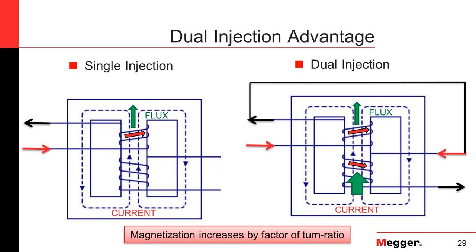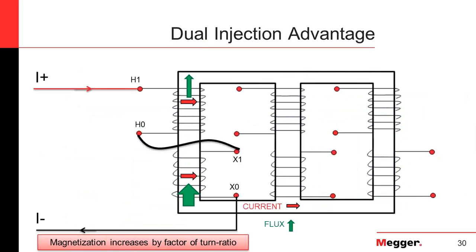One of the areas that we've found recently, I'll say actually it was quite a while ago, but as far as practices goes, we can magnetize faster by using 2 windings in series because of the factor of the turns ratio, not only because of the fact that we're doing 2. And so we get a much bigger, faster effect on most or many transformers by performing a series test. So here we see on a 3-phase core, this is a typical construction where the windings are connected in series such that the flow runs in the same direction.